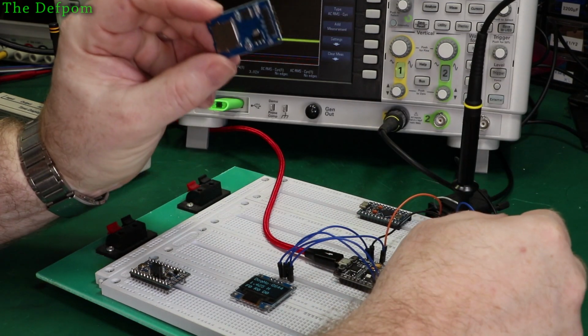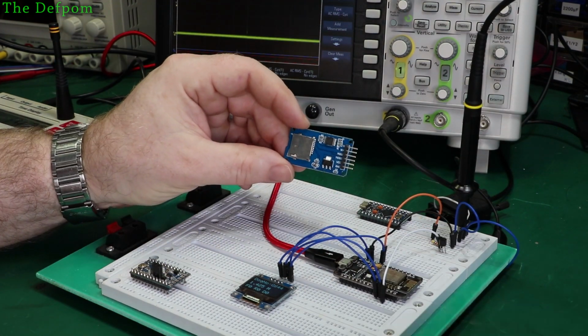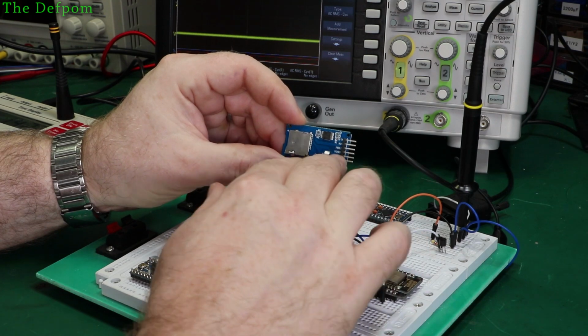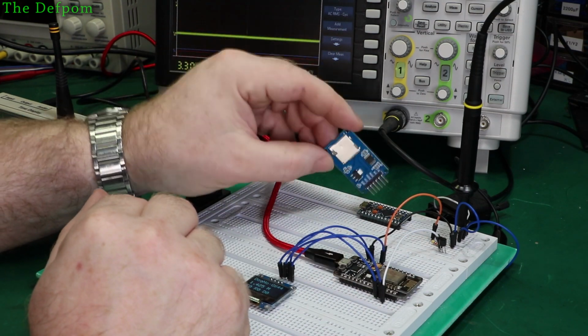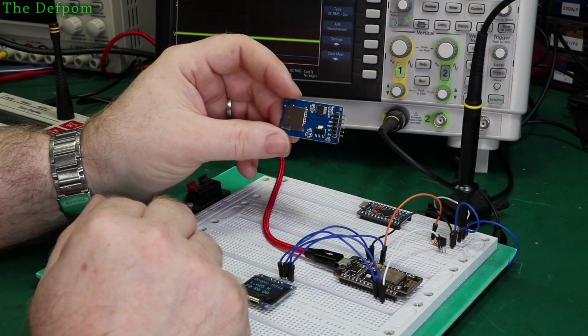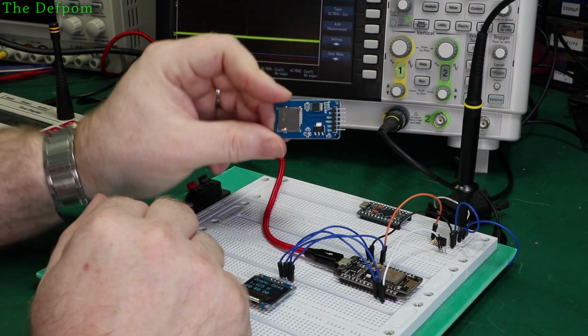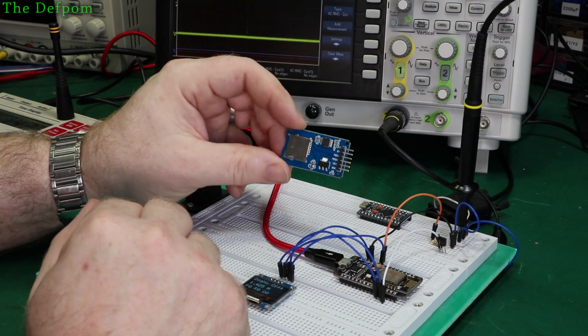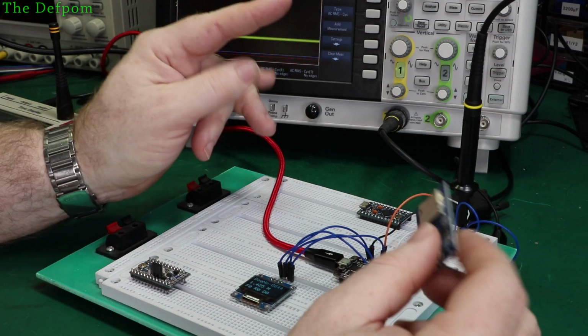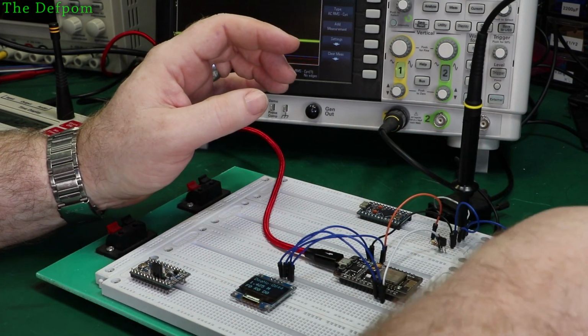Those are the two things I'm trying to achieve. It was okay until I went to do this. So the problem I had is that the MicroSD card libraries caused me to run out of memory on the Pro Micro. So damn, this kind of ruins that, because I want to back up onto an SD card. It's quite important. It's got a backup as well as going through the network, in case there's a network failure, for example. At least then it won't cripple the system.